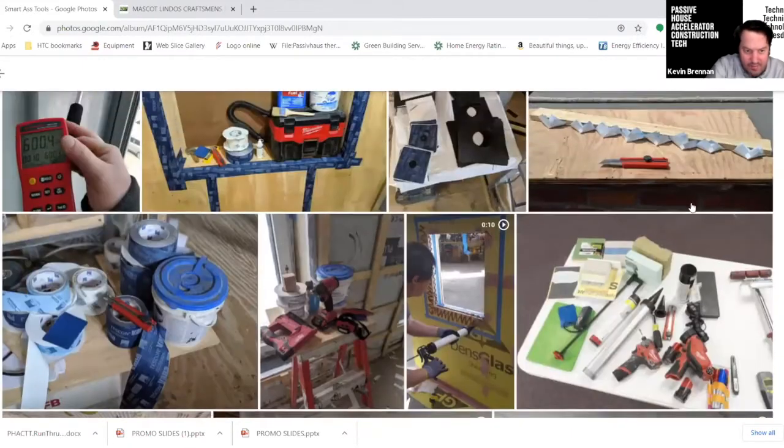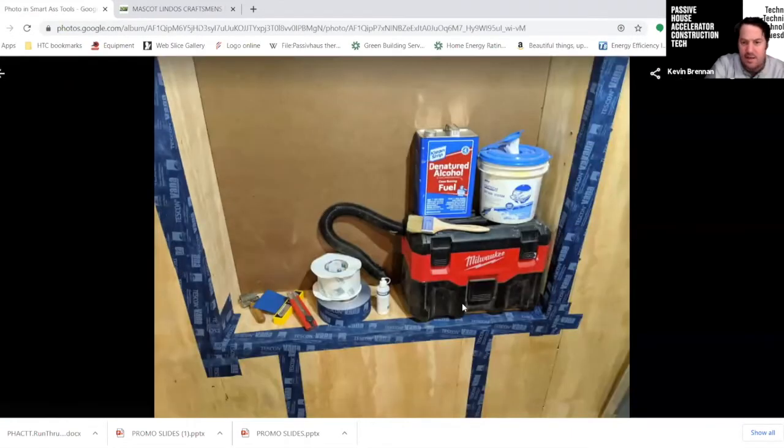Leading into that, this is my on-site setup. My on-site setup is really denatured alcohol, the wipes, the vacuum, some primer if I need, and then my Tajima blades with backup blades for myself and the guys, and then the press fix and the roller. And this is the type of work that it produces, and it should be clean and neat and dry and look professional and be professional.